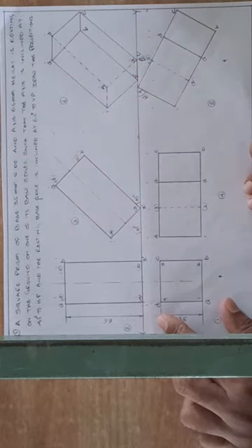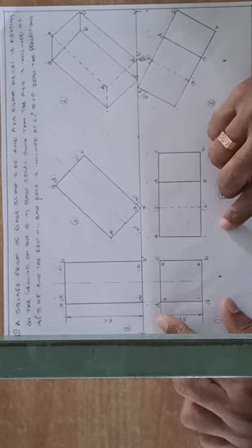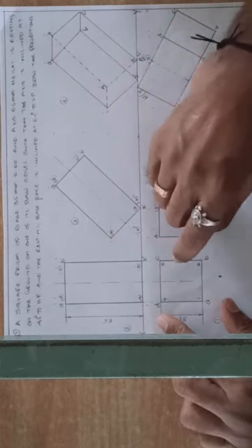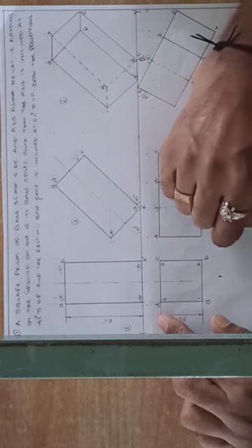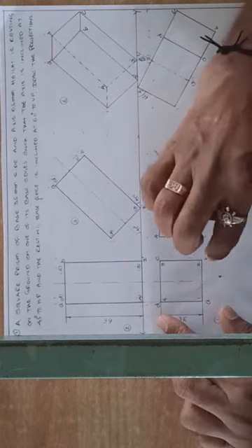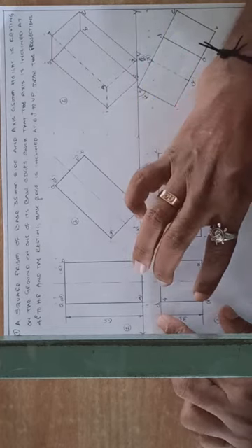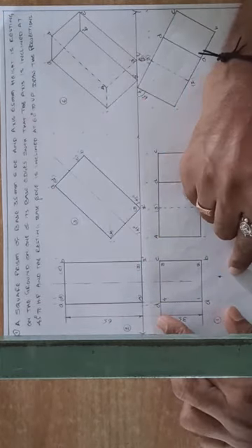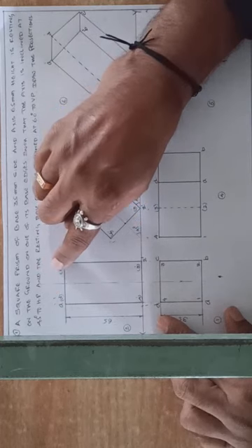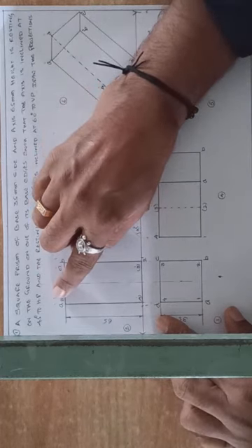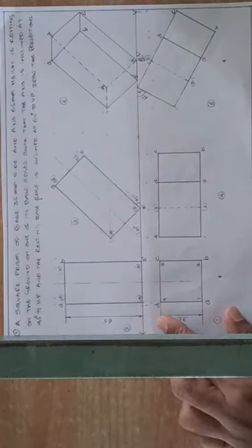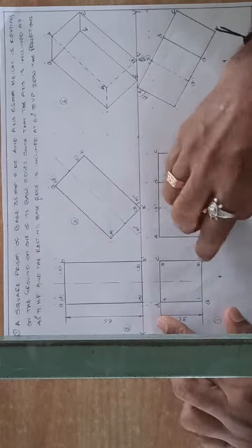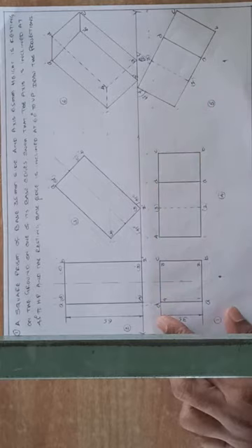Now draw the projections downwards. Again horizontal projections from the top view. And before that, notations, already you know how to draw the notations, A, B, C, D. And for the prism the bottom face 1, 2, 3, 4. Here looking from the front, A visible, B visible, C is not visible, D is not visible. Similarly 1 is visible, 2 is visible, 3 is not visible, 4 is not visible.